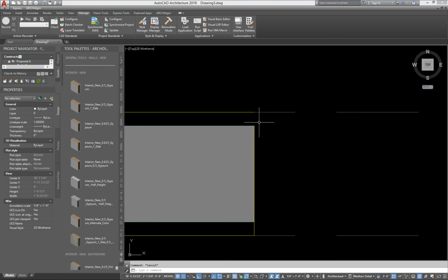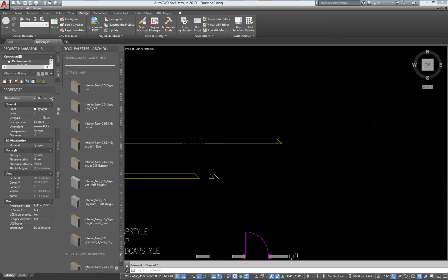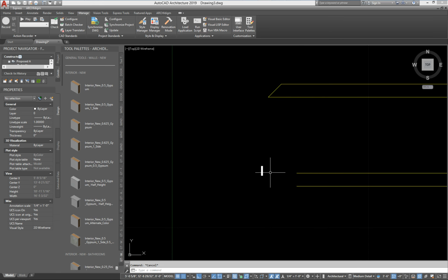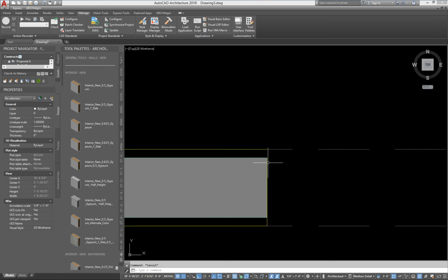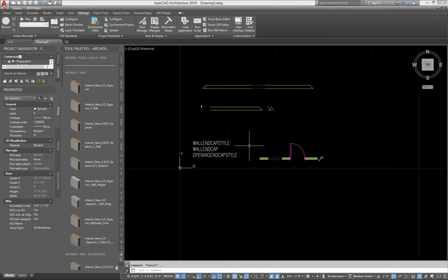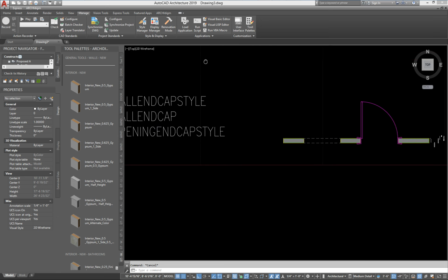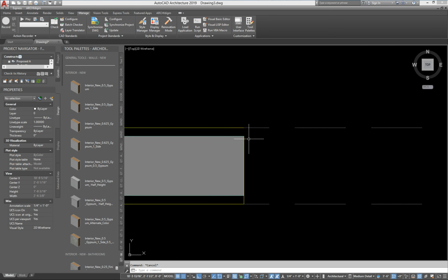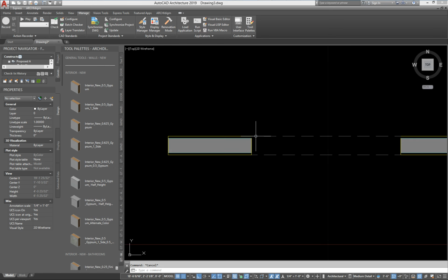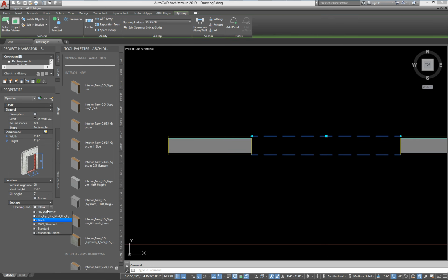Now the blank, isn't this funny? I'm glad I just did that. Because I only did the one component on that, it's taking the first component and blanking that out. So you'd have to select this 3 times for each of the 3 components to blank them all out here, because there's 3 components. But it did do that one. Let's go ahead and set this back to by style.